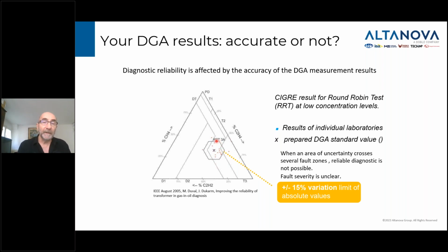And that's why the standard says that you don't want to be more than 15% on that accuracy, and even better. As the accuracy improves from 15%, let's say, to around 5 to 6%, that surface shrinks significantly around the optimum diagnostic point. What it means is that the accuracy of that diagnostic increased significantly, and that's mostly what everyone is trying to get during a DGA.